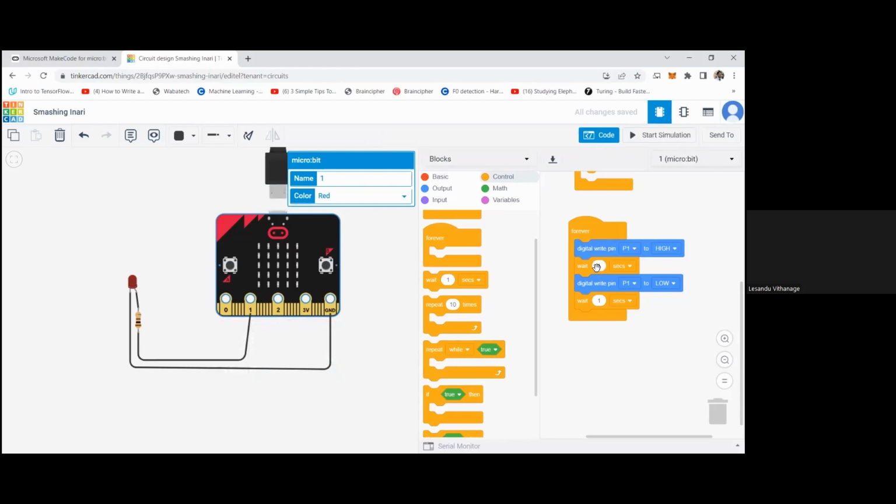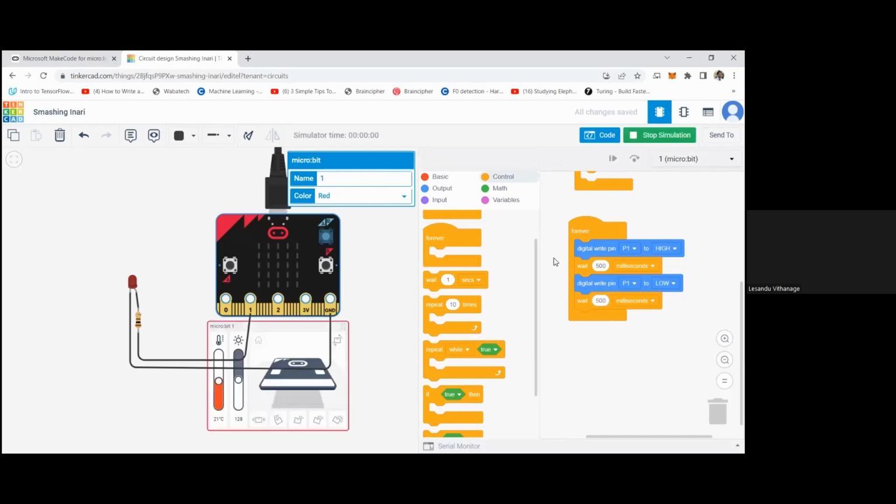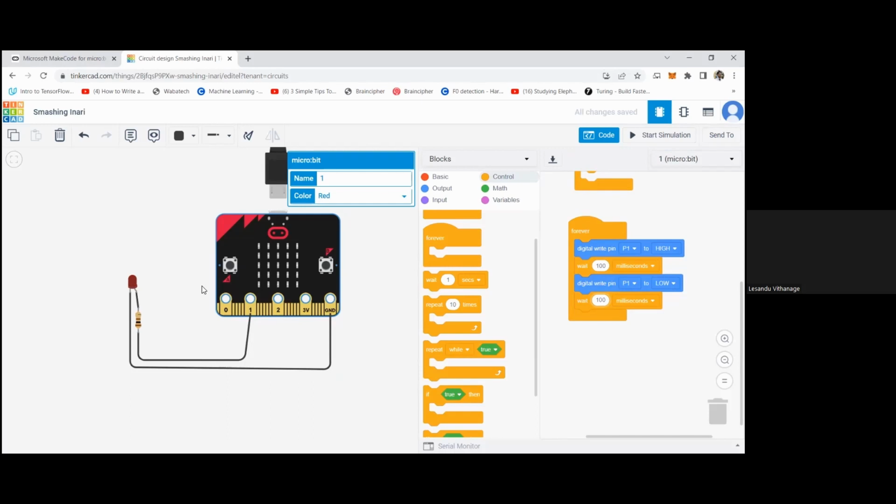We can go here and, instead of seconds, select milliseconds. 1000 milliseconds is equal to 1 second, and I will change my value to 500. So it will be half a second, 500 milliseconds, and I can run it. Now it is much faster. Let's say 100 milliseconds, and now it is even faster. So that's how we can make the LED blink using the GPIO pins.